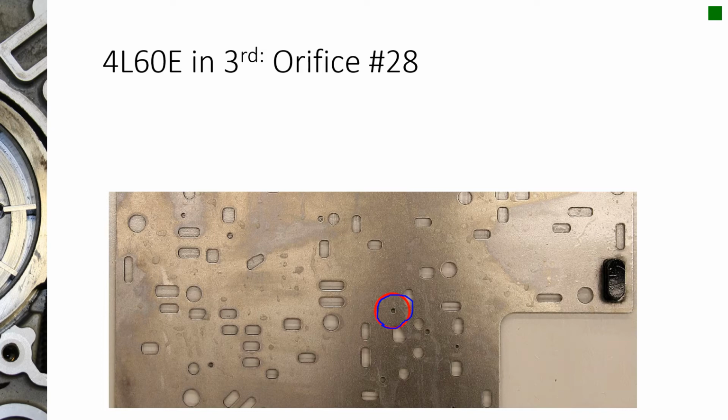So now I've got two engineered bleed orifices that are always passing fluid. And if I created some other leaks, maybe through Teflon seals, maybe through a slightly cut piston seal, or a bad connection on the spline or something, every time I create another leak, if I ever get to the point where I come close to the size of that orifice, by the time you add up all these leaks, then I can't maintain pressure on the other side of this orifice, and I could run into a clutch that slips and burns up. That's the reason why this 3/4 clutch is also kind of